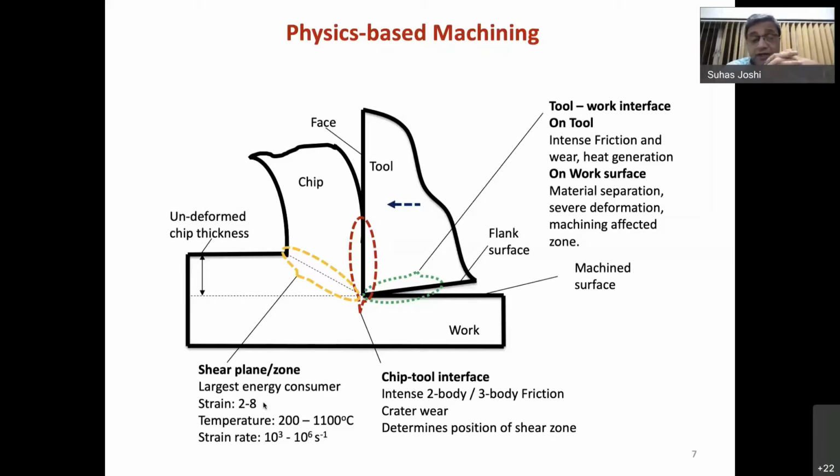We call that a single point diamond turning machine. With a single point diamond turning machine, you can remove ductile chips from the material which are of the order of a few micrometers in thickness. The technology has reached a level where it can slice the material so easily, and such thin slices or chips can be removed. So, nevertheless, these are the issues they have overcome.